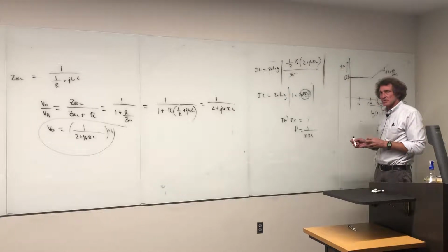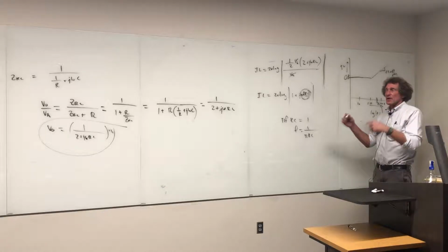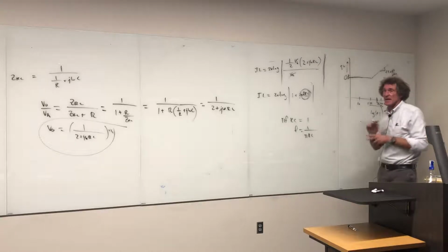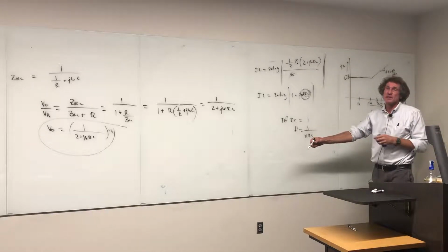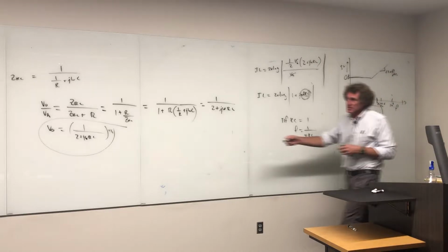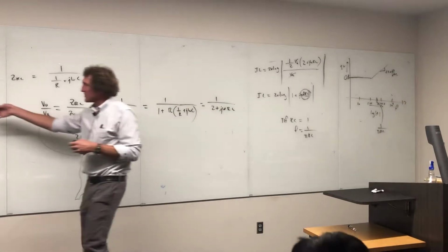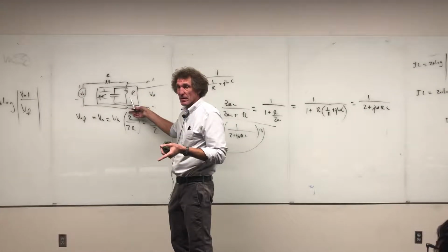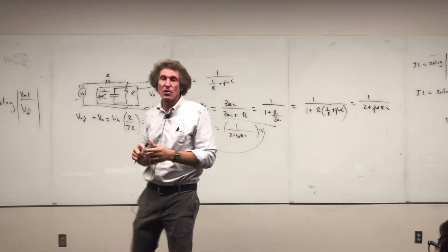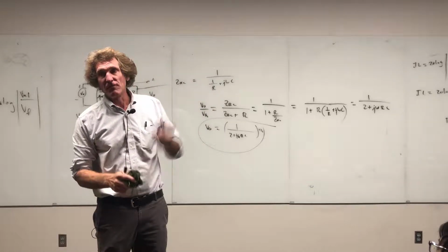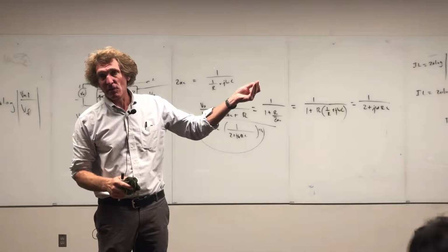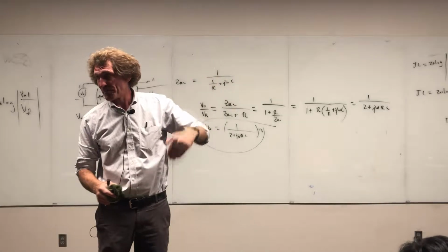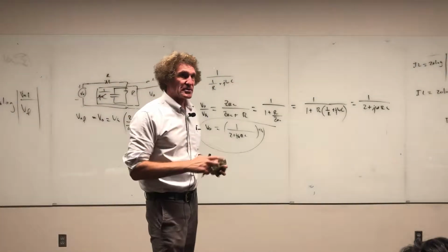This is always used. Now, one other thing, loss. If I'm thinking about this, I'm almost thinking this is the filter's response. That's exactly wrong. The actual filter's response goes down, right? Because this right here is going to be a low-pass filter. Just look what happens as the frequency goes up. The capacitor looks like a short circuit. You have no output, right? But because they talk about insertion loss, what we're doing is gauging the amount of loss. That's the reason. It's truly a loss. So in a sense, a positive loss means the output signal is going down. That's what the effect is. Got it, class? Any question about this?